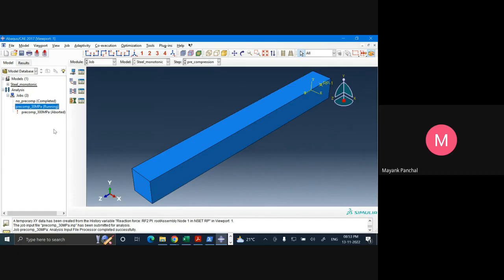You can fix the bottom part of the wall. Okay, and define the reference point there, and then I showed you a rigid body constraint, and then request force and displacement from there. Then at the top of the wall you apply a horizontal loading along the length at one edge, and see how the force displacement response is, and try to fail it by increasing the load.